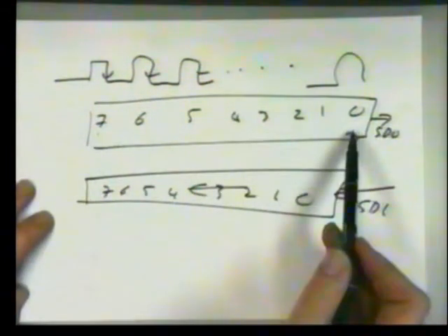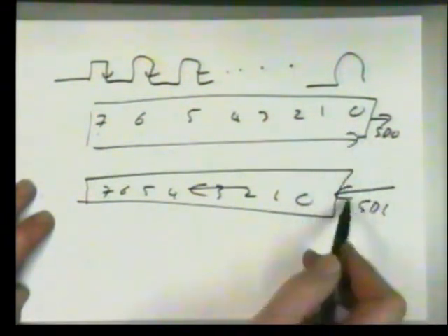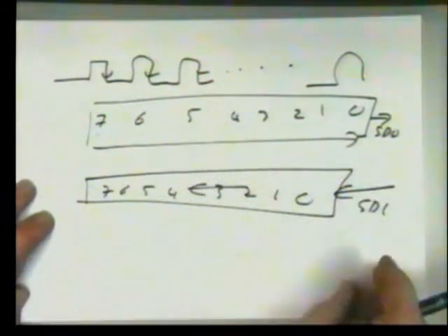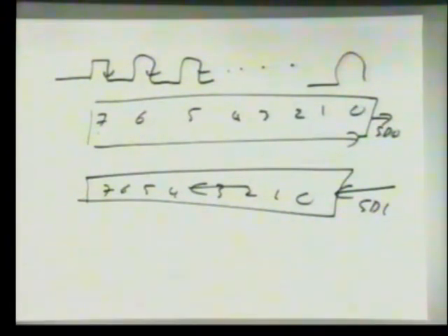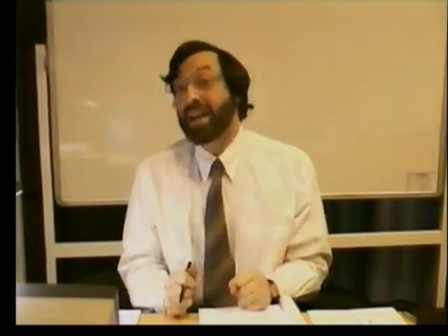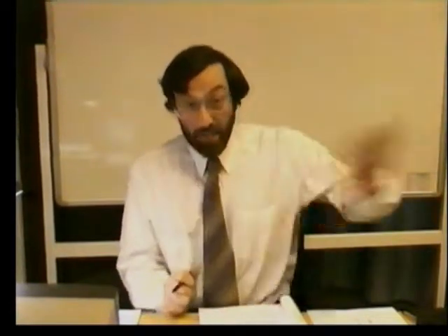If you've just started the transmission, so let's go back to this picture. Here's the first byte we output on serial data out. What is this data coming back from the slave? Well, it's rubbish. It has to be rubbish, because the slave has never received a command. How does it know what it's supposed to send back? Something will come back, but it's garbage.